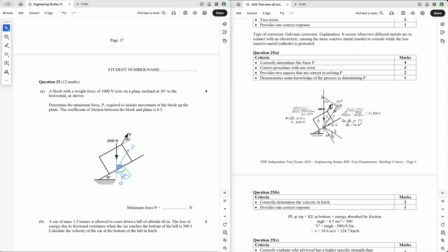Going clockwise, the next force is BC. It goes through B and it just projects up there. And the next force is CA and it's got to go through A. So you just transfer that angle up here. And so you've got your force diagram.